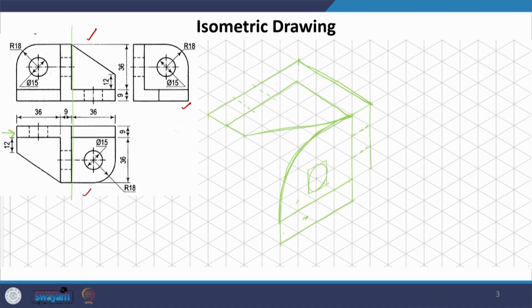We also see that there is a separate line. Here there is a solid line, which means that this surface is not the same as this surface. It is not a continuous surface. We have an inclined line, which is what we get when we look at this surface, which appears to be an inclined surface, not a flat surface here.